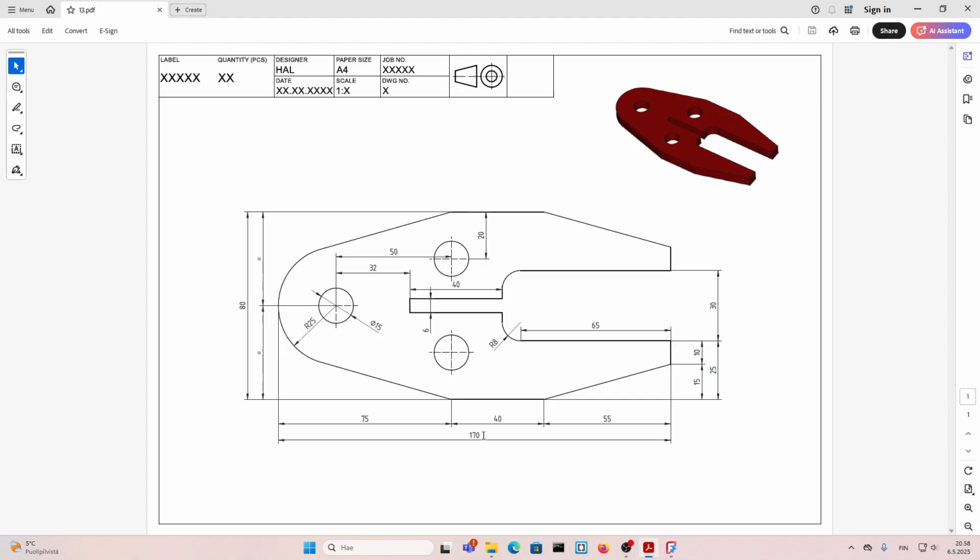If you look at the piece, it's 170, it's in the center. 80, it's in the center. That's what this 0, 0 point means. So if I want to add a point on here, 170 divided by 2, 85, and I have to go to this side, so it's negative 85, and the y direction is 0. So negative 85, and I can get a dot onto here.